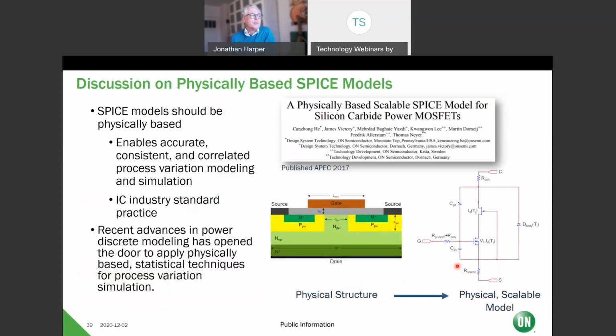The other thing is simulation models. onsemi has been very active on physical models, and there's been a lot of development on IGBTs. The same thing is we have physical scalable models for silicon carbide. The scalability is maybe of less interest for a customer. Okay, we can scale it and I can make a die size what I want to, right? But for a given die size, you can get accurate modeling of the effects, for example how the diode works, the capacitances of the diodes.